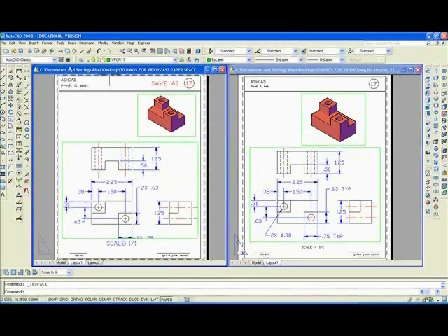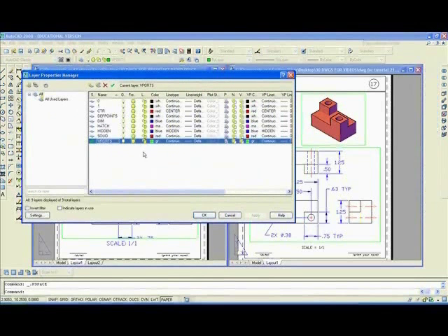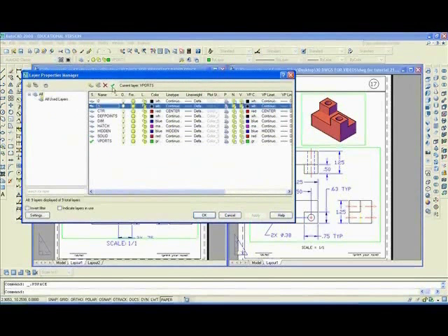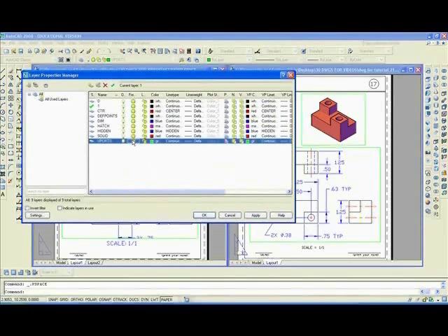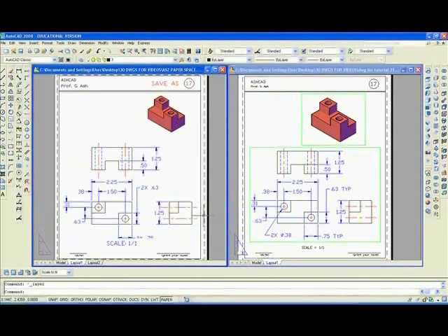Go here to layer 1, current, freeze viewports. Now I can say that the drawing is complete. I want to thank you very much. Oh, that doesn't show in the bottom. I wonder why. Well, we know why. We can just move it up in the viewport. Thank you, and we'll move on to exercise 18.